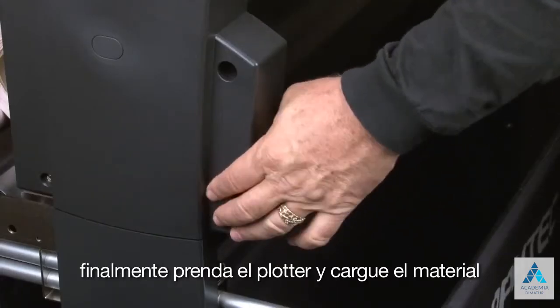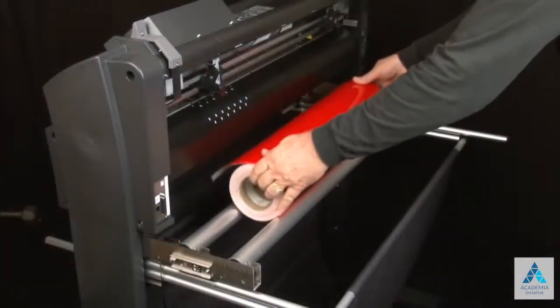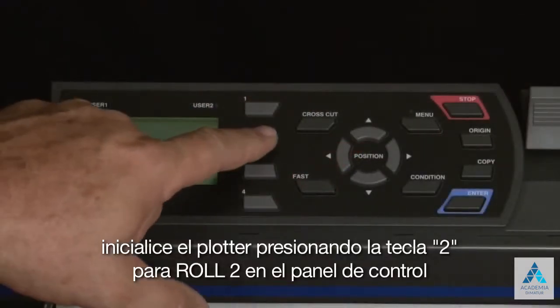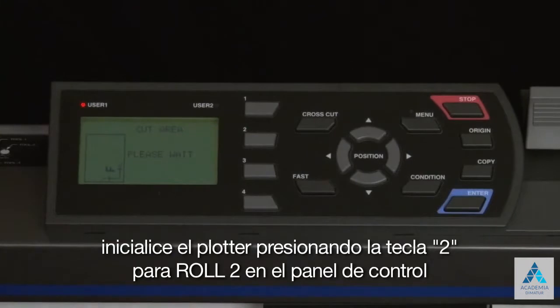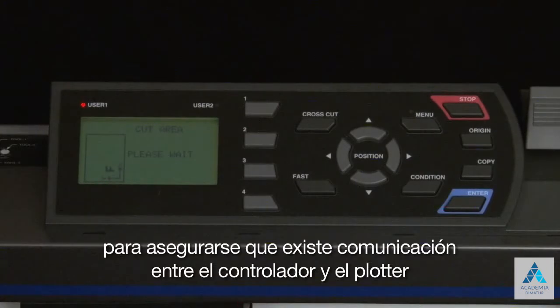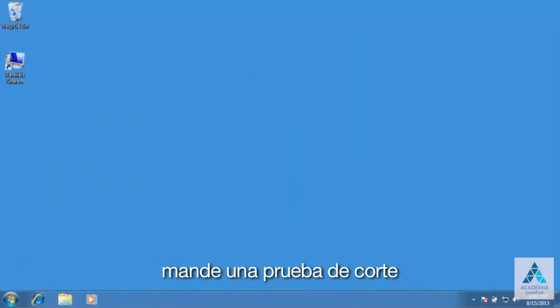Finally, turn the cutter back on and load the media. Initialize the cutter by pressing the 2 key for Roll 2 on the control panel of the cutter. To make sure that there's communication between the controller application and the cutter, let's send a test cut.